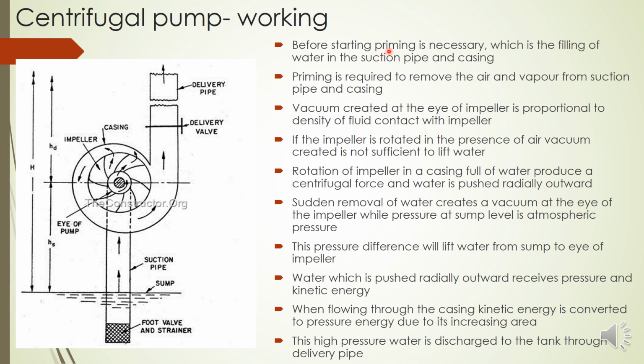Another important thing is that priming is not required in every operation. Only in the initial phase do we have to do priming. If you are operating on the first day, we have to do priming. On the second day, the water from the first day will still be here, so you don't have to fill water again. Priming is required only in the first operation, or if some leakage of the foot valve happens.